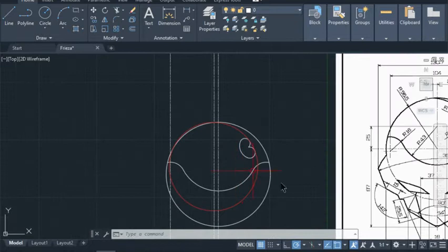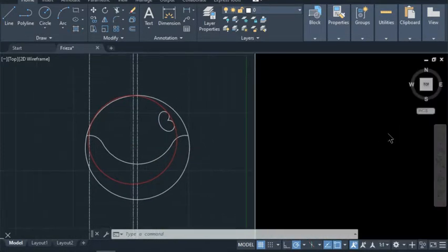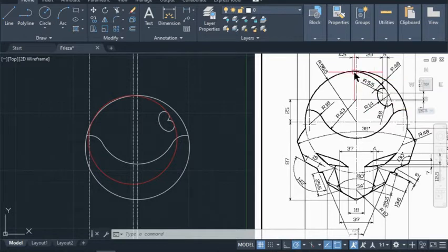So again, if you did not get that, there is some subtraction that we need to make, because the circle that intersects these two small circles that we created earlier with the radius 48 is not crossing at the location that we want. So we need to move the circle up a little bit. To do that, we create the circle from that center, and then we create another circle from the same center of the 5.5. Subtract that 5.5 because that's the arc that we need to connect to. And then we got the intersection. Now you can go back just a few seconds to see how I did it.